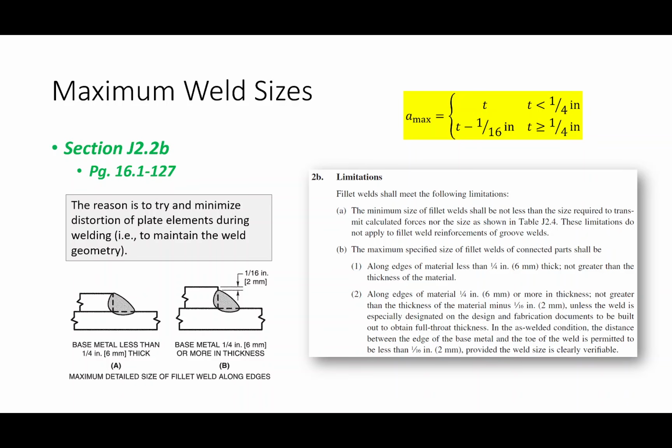Okay, so I'm placing weld. As I connect that circuit, I'm depositing weld metal. So essentially this bubble's getting bigger and bigger and bigger, okay? And I'll talk about multiple passes of the weld in a bit. But what happens when the weld gets all the way up here, all the way to the very top? What's going to happen is this corner of the plate right here is going to start to melt, okay?